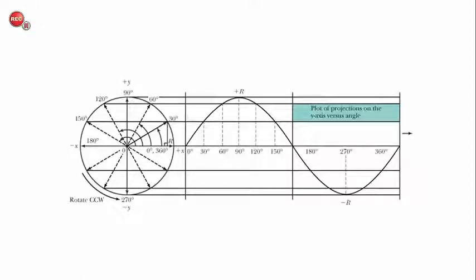And so if you could imagine flux lines from a permanent magnet where the north pole was at the top at the positive y and the south pole was at the bottom at the negative y, and if this arrow represented the position of the conductor, when the conductor is at 0 degrees and moving up, it's moving parallel to those flux lines, and no voltage is induced. And so that's what we see here in this graph at 0 degrees. Here at 0 degrees, there's no voltage being induced.